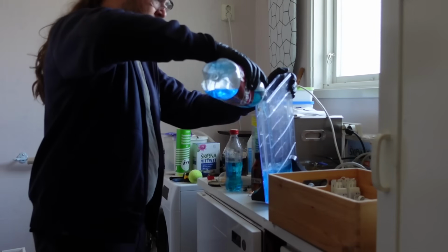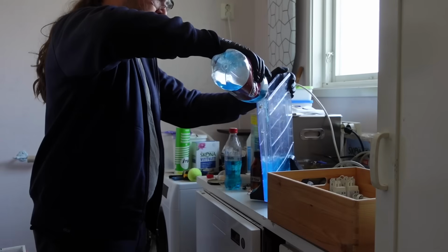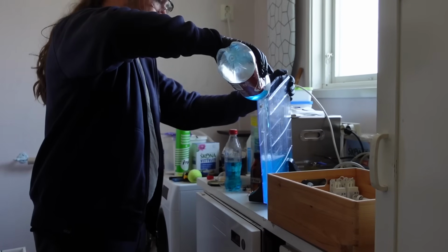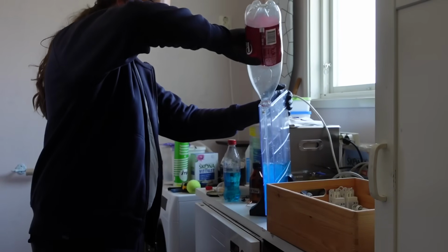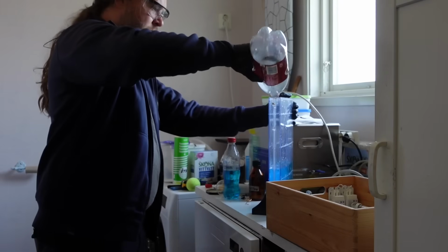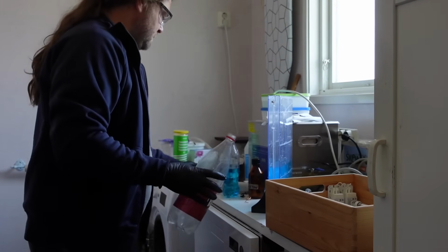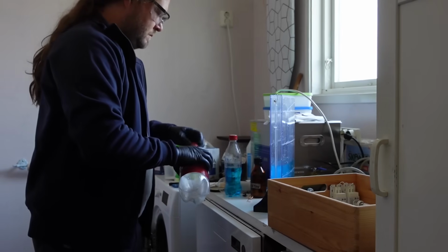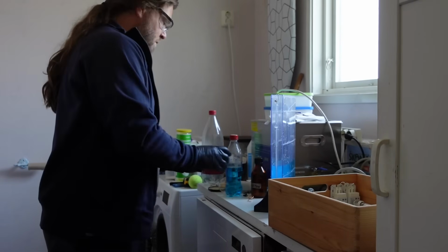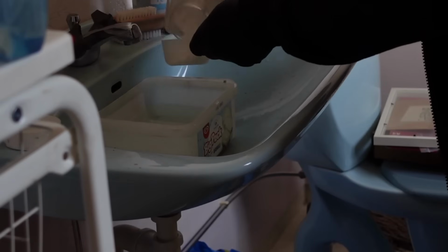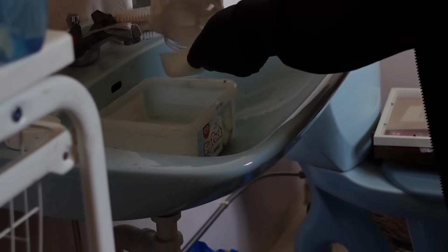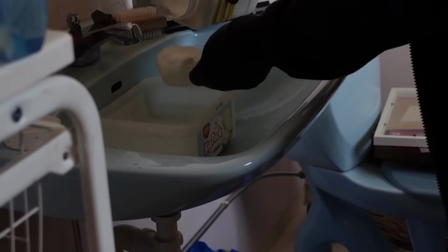So, step 1 is to prepare the etching solution. It'll take a while to heat up, so it makes sense to start with this. Used etching solution keeps well, so we'll start by just adding whatever's already sitting around. The blue color comes from copper sulfate, from previous board etchings. It wasn't quite enough, so we needed to make some more. We're using sodium persulfate, which keeps well. If it's been sitting around for a while, it might get a bit lumpy, but it should still be fine.